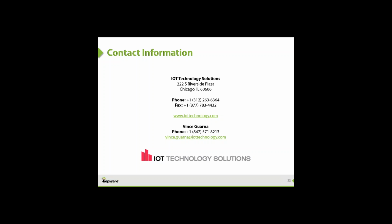Absolutely, and I apologize, I meant to mention that during my presentation. If you remember that notifications tab when we looked at alerts, we had options like email, SMS, voice, MQTT, and HTTPS. The MQTT and the HTTPS web service call would be our way of doing that. For example, the IoT gateway is acting as a client here, but it can also act as a server. We might want to, in response to an alert, issue a service call back to the IoT gateway, which tells it to turn on a stack light, for example, or sound an alarm. Or we might want to publish something to an MQTT queue that some other machine on the manufacturing floor is polling to get the information back. So yes, you can definitely cause control actions to happen in response to alerts.